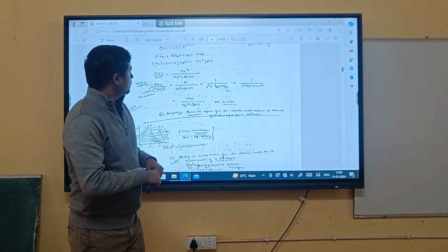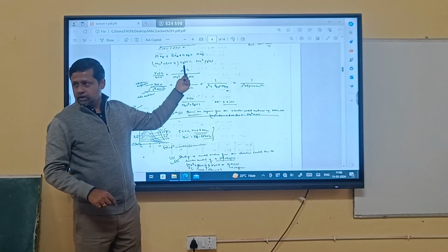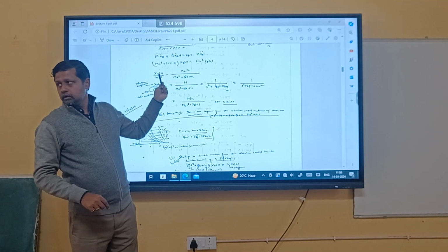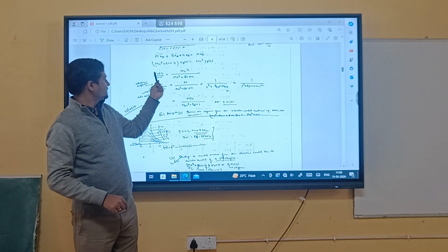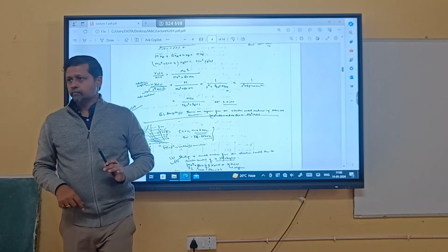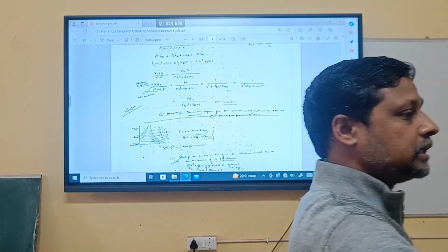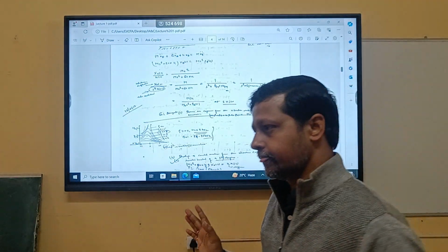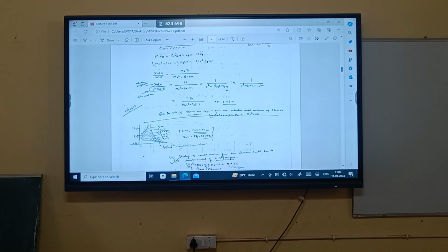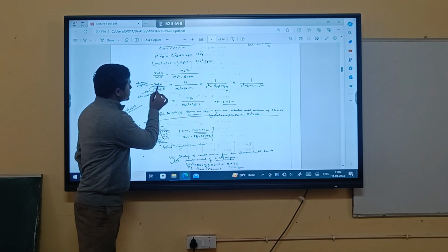Which one is the independent domain? This one? Shift this to here. So remodify your transfer function. Rather than x naught by xi, you write it x naught by s square xi. Why s square? Because remember it's a second order system. If it were a third order system, then it would be s cube for sure. If it is a first order system, then it is s. Idea is clear? Because we are doing the second order application, here I am taking s square xi.